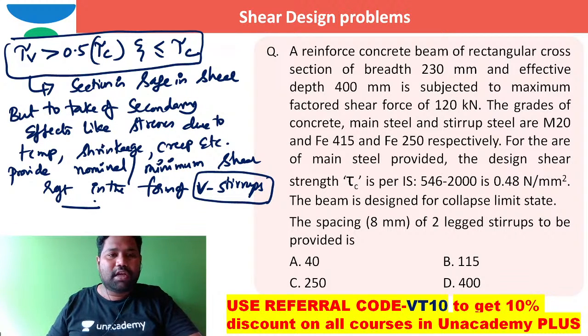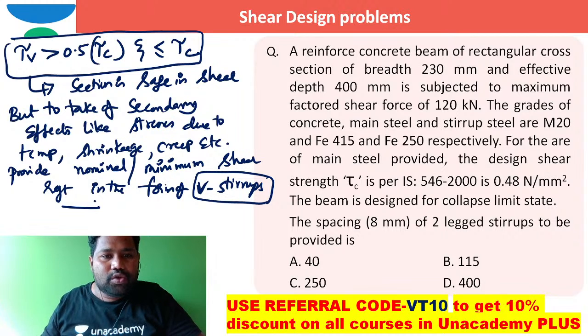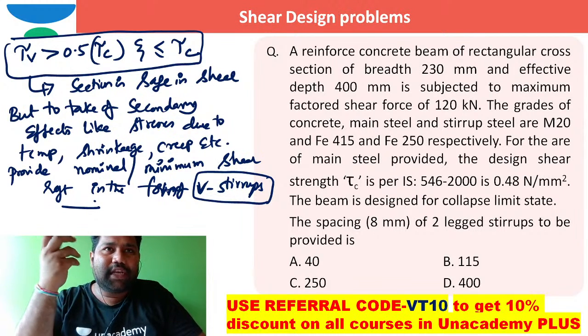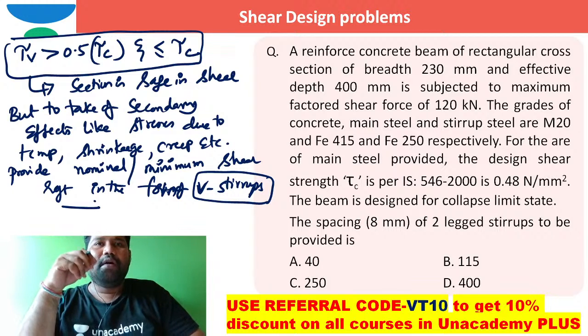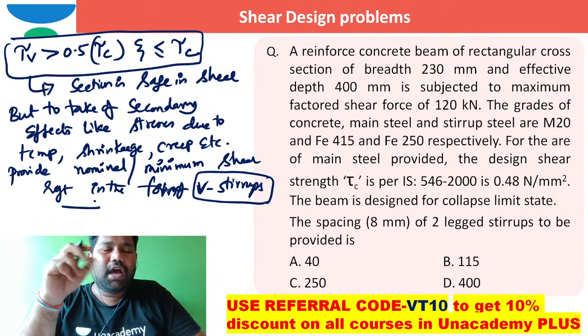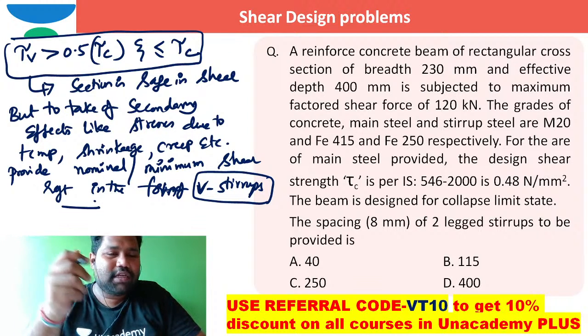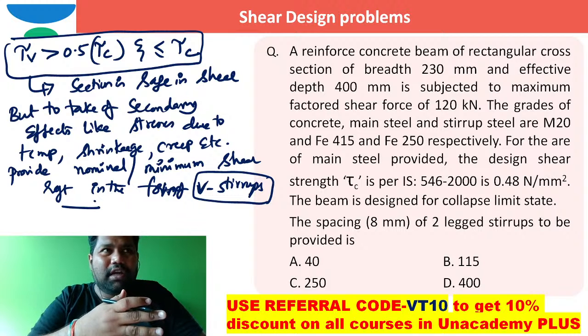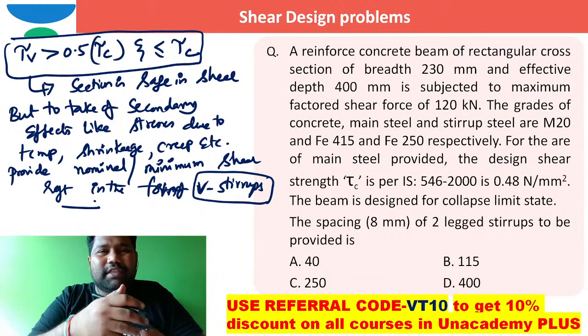That's why the code says use vertical stirrups. In terms of shear reinforcement strength, inclined stirrups are more effective, but they are not stable in the cage reinforcement. So that's why the code says to use vertical stirrups when you are designing for minimum or nominal shear reinforcement.